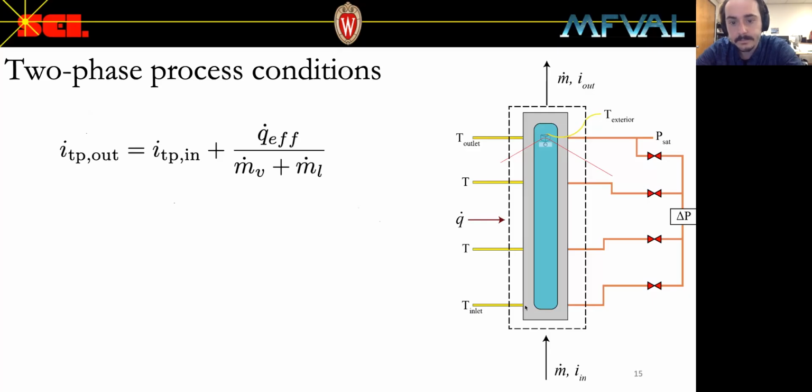I see. And what's the current time constant of the thermocouples that you are using? The thermocouples within the test section have a slow response, within a second or two. The time lag for the exterior thermocouple is about 5 seconds, and that's associated with the diffusive time constant through the window. The response of the thermocouples in the test section is not very good, but it's not totally necessary, because these thermocouples measure the temperature, and then we compare that with the saturation temperature that we get from the absolute pressure measured here. So basically these all measure saturation temperature during two-phase flow. Okay.